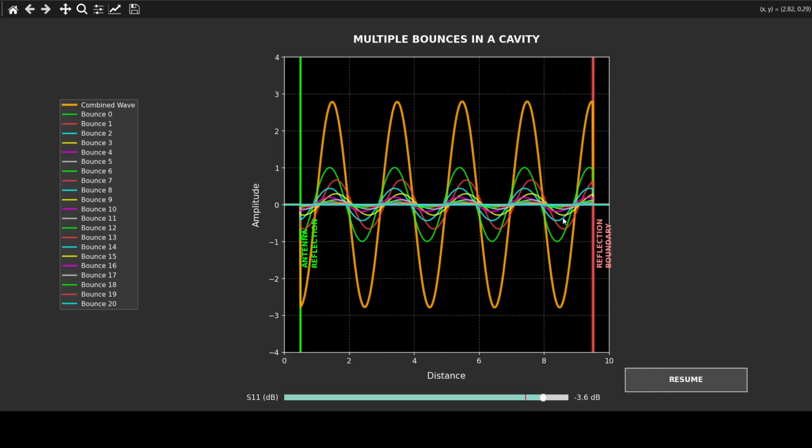These reflections are not just limited to wireless communication, they can also be in wireline communications. Especially when you have short channels, the distortion that reflections cause to your signal can cause bit errors and make the signal you see at the receiver more distorted. So I guess this is one of the things I wanted to show in this video: why impedance matching becomes important when we are designing an RF circuit.